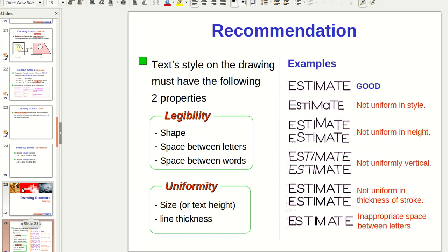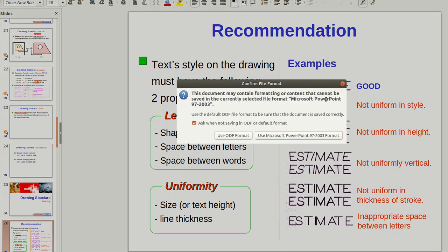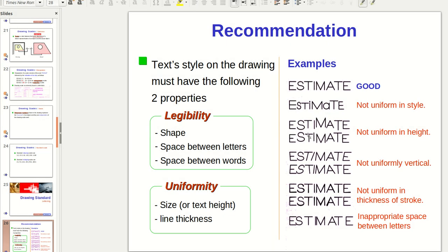After that, the last thing is writing. Usually you see writing in the dimensions or on the paper of your drawing in general. This writing is supposed to be like this, large or upper case letters like this in one line, not like this one, with one upper case and one lower case, or upper and lower. It is supposed to be in between two lines, from 2 to 3 millimeters. So it is easy to read, easy to write, easy to understand. Anybody can see it and understand what this writing or these numbers are.